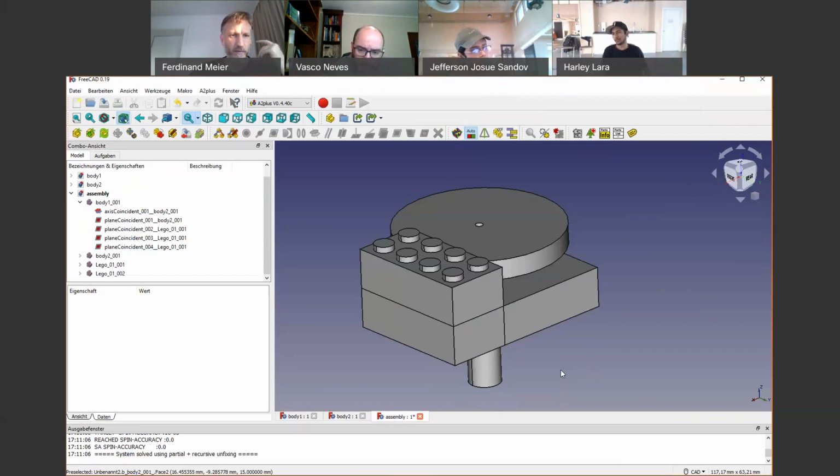You can also do the same trick in Fusion, where you make a sketch and then you export the DXF. But for me, that's an extra step that I don't need. If I make a drawing, I can neatly arrange all my pieces. I can make my drawing size exactly the size of my laser cutter, so I can tell if it fits or not. If I have a funky piece of material that is left over from something and I want to cut exactly on there, I can just quickly draw it in FreeCAD, put it in my drawing, and then arrange my pieces so that they fit on there, and then it will fit on the laser as well.